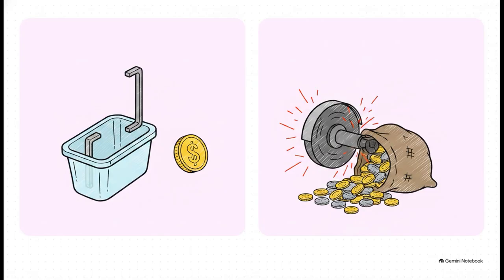As an auditor, you have to verify if any tolerance is obviously tighter than functionally needed. Is there a profile tolerance of 1/1000th of an inch on a bracket that literally just holds a plastic cover? Or is a tolerance tighter than your shop's machining process can actually hold without resorting to super expensive secondary grinding operations? This step ensures the print isn't just legally correct, but actually commercially viable.